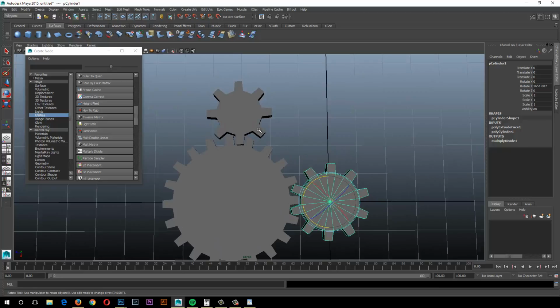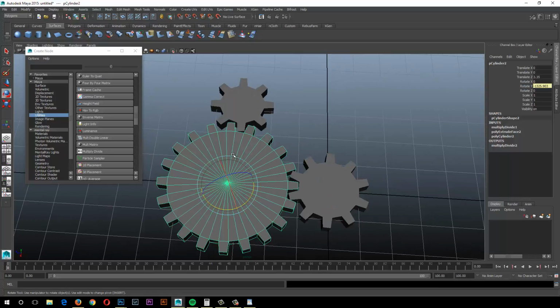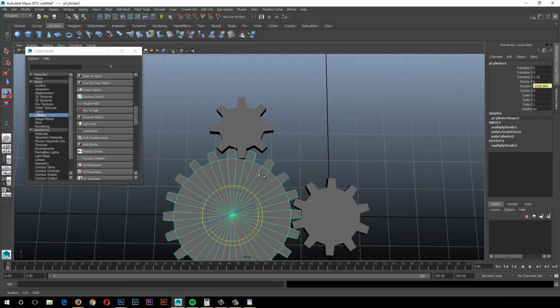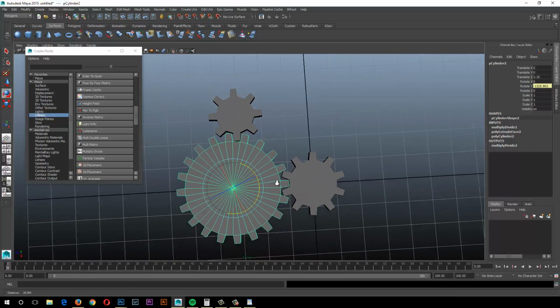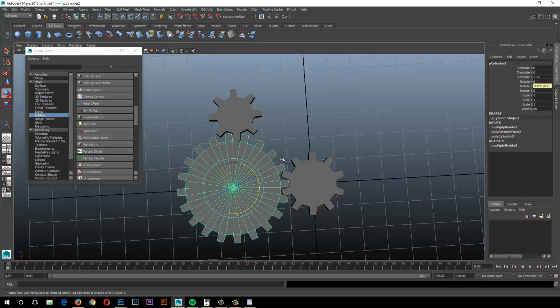Now, if you did have something that you want bigger teeth on, the way you do that is the same way you do in actual gears, is you have another gear that's riding the axle of this gear that then has the bigger teeth that you want, that has a different diameter that then could hit another gear with different teeth. So if that's the kind of thing you're building, just keep that in mind, go look at a watch and how the gears kind of stack, or anything else with gears actually. If they have something that has different teeth size, it's usually on a separate gear. But the one that it's actually spinning with has teeth that are the same size. So that's the main key, is just teeth need to be the same size, so you need to do a little bit of math to make sure that that actually happens.